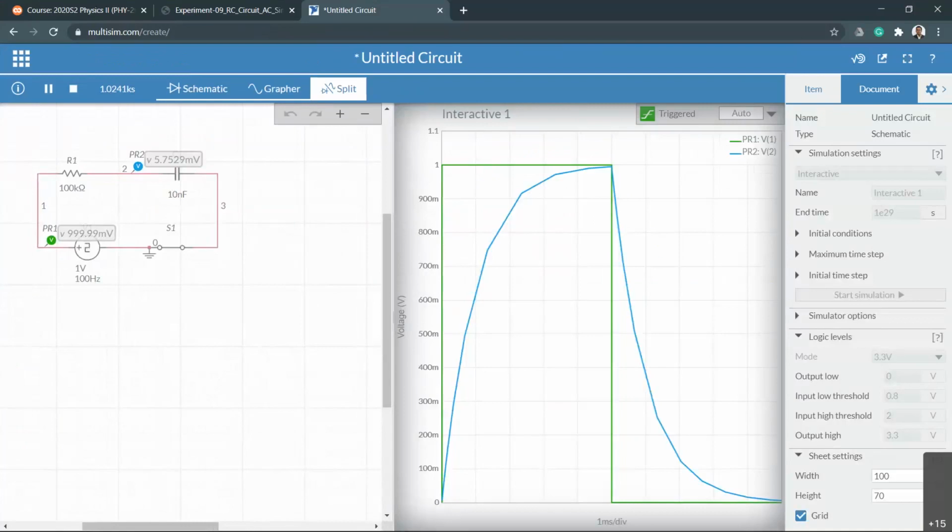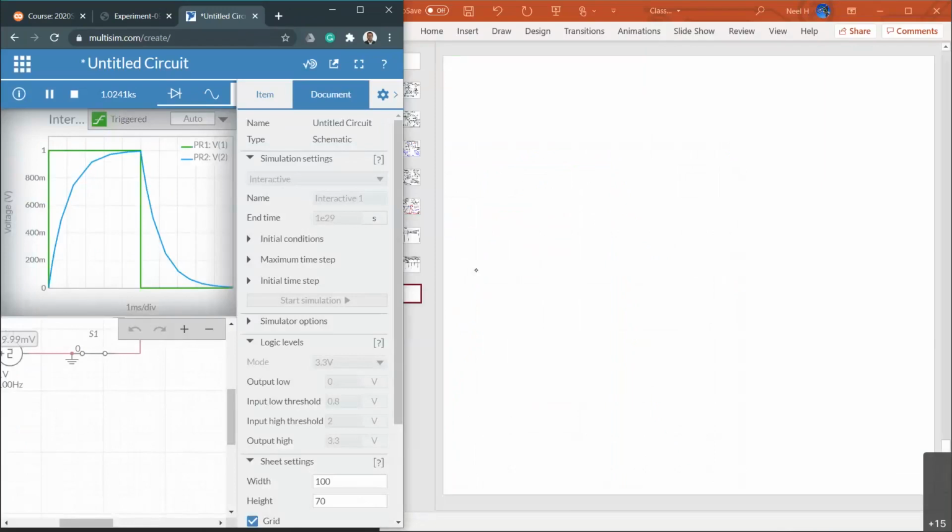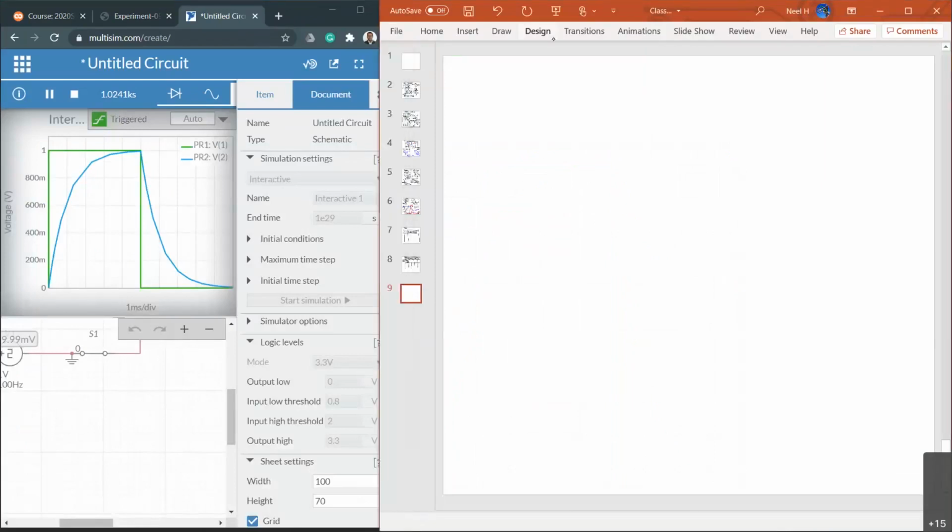Any questions so far? Now for the charging graph, what are we expecting? You remember we discussed that earlier. The charging graph equation should look like this, right? Vc is equal to V0 times (1 minus e to the minus t over tau). When you place t equal to 1 tau, one time constant, you can find Vc at one time constant equal to 0.63 times V0.